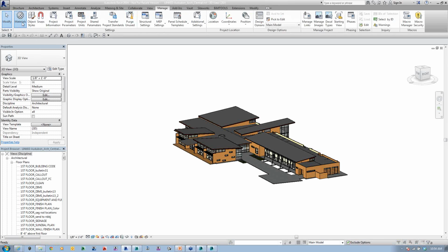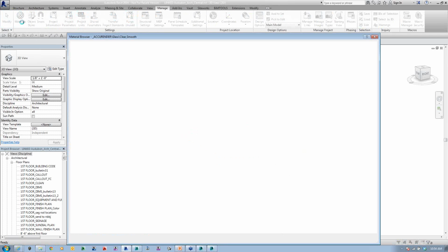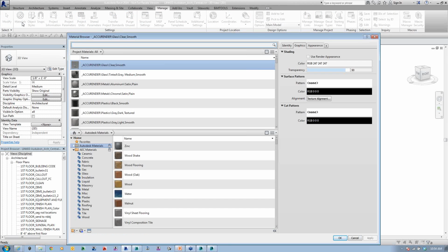Okay. Kirby asks, once you have defined materials for objects in Showcase, can you translate those changes back into the Revit model? In other words, is it backwards compatible? Showcase is not backwards compatible, so whatever materials you have in Showcase will not push over into Revit. 3ds Max does have some capabilities of doing some of that.